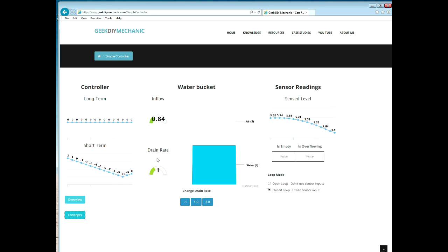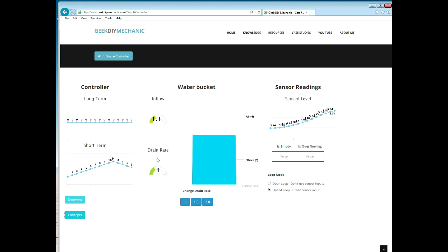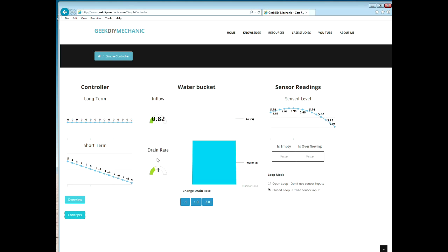So, real quick, the reason why they have short-term and long-term fuel trims, especially short-term, it helps. As the car ages, obviously the sensors aren't going to be as accurate. So short-term and long-term fuel trims can make up for those and still make the car very reliable and drive great and still be clean at the exhaust. So that's why these can't be constant values. This is a way that allows it to adjust.